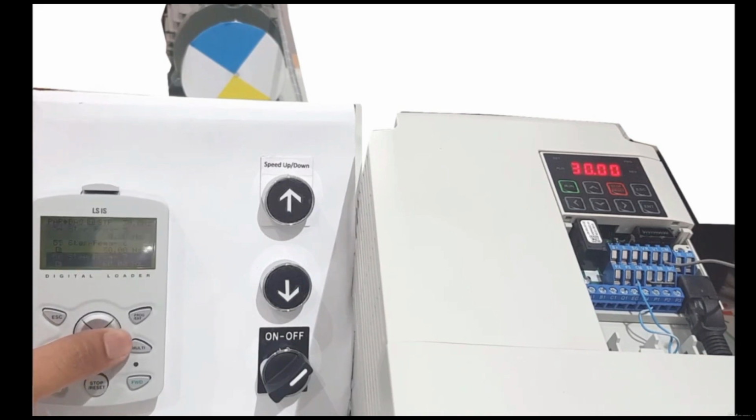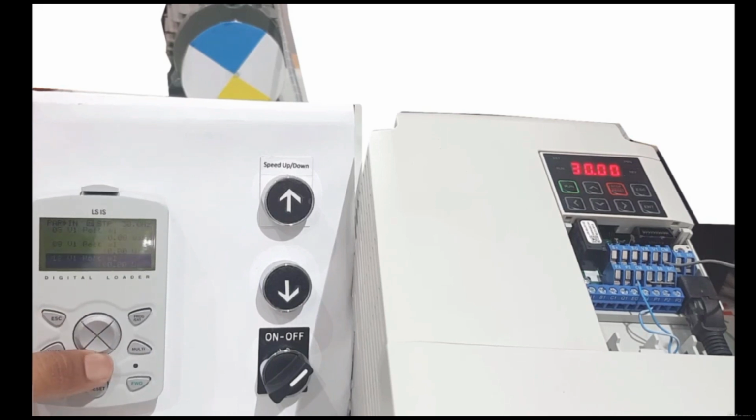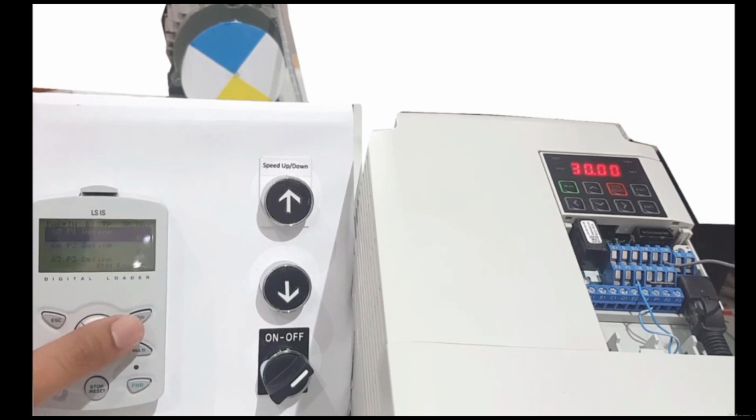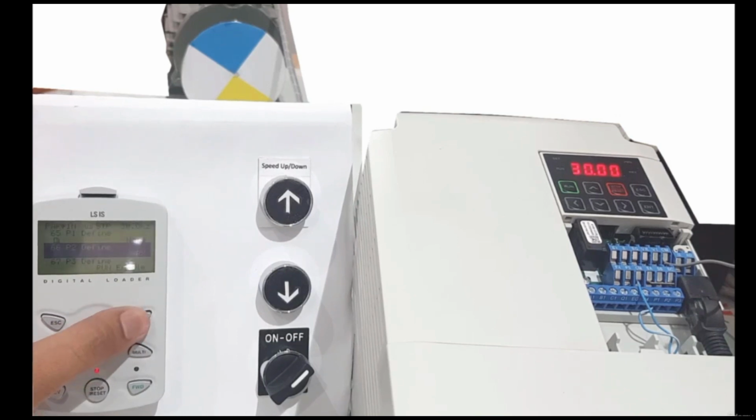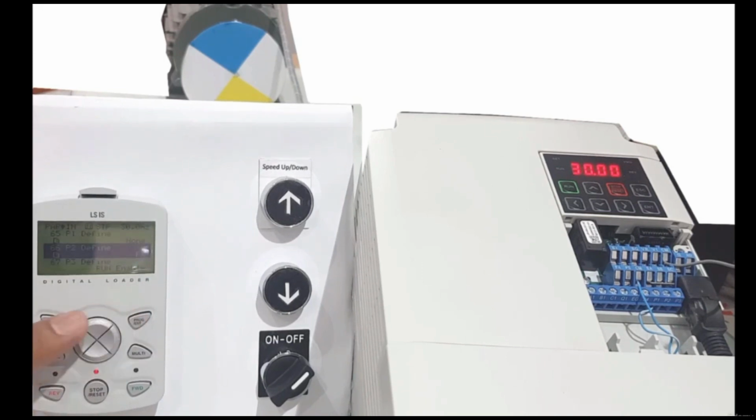First thing, you should know that duplicate functions are not allowed. So that means if I want P2 as forward function, first I must remove this function from P1. To access P1, I will go to parameter IN65 and I will select none, which is number 0. Then I will assign forward to P2. I will go to parameter IN66 and will select FX.